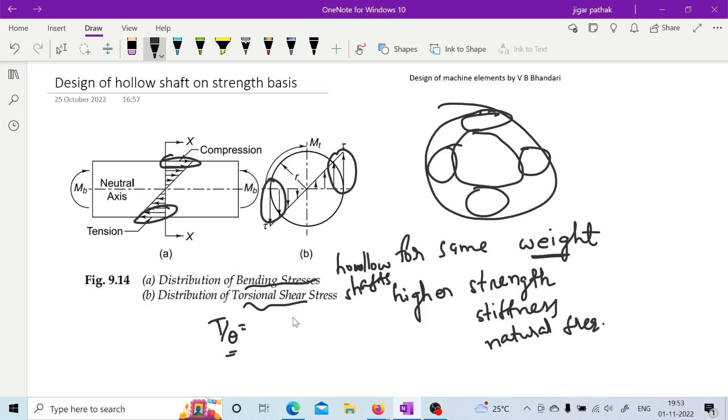Yes sir. So under root, natural frequency will be what? Under root KT by M, right? The torsional stiffness KT is generally calculated from this T upon theta. Yes sir. But still you need to verify, right? I remember a little bit of that and I'm sharing, but still verify that, okay?